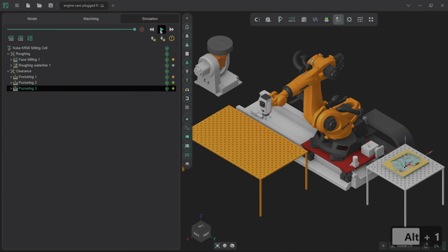Hi. So this next video is going to be about the surfacing operations that we're going to use to clear up the flat planes in the model and then start working into those rolled surfaces as well. So the first setup stage that we're going to be putting together is going to be using an operation type called Flatland, which is very good for clearing out large flat regions and keeping them nice and clean.